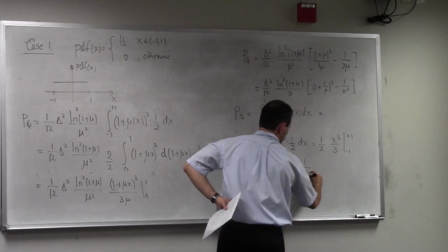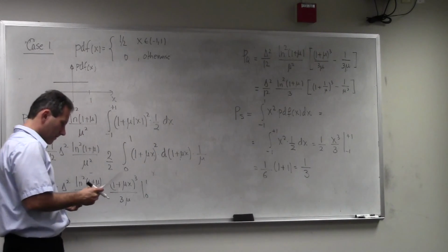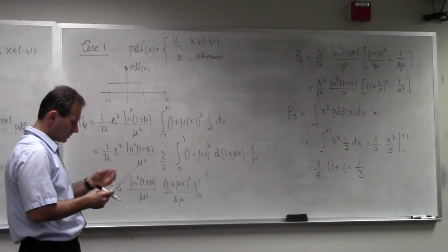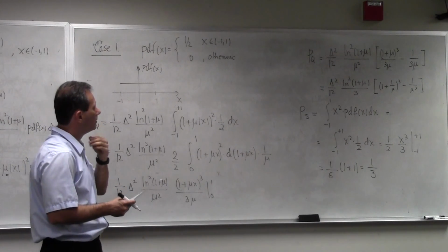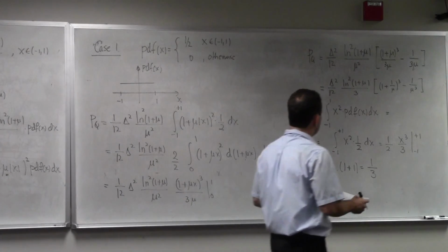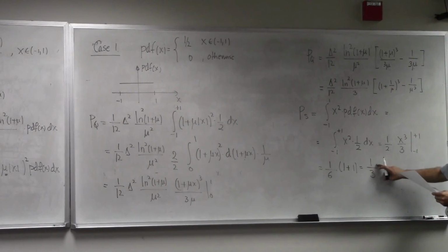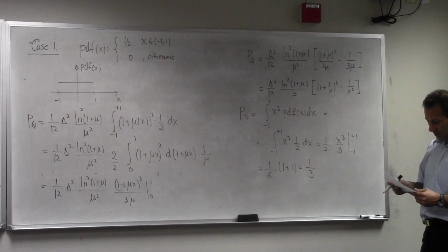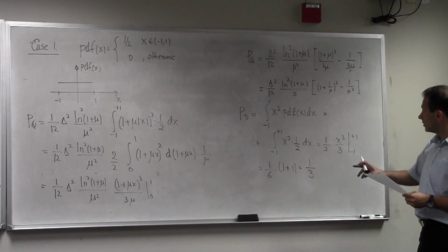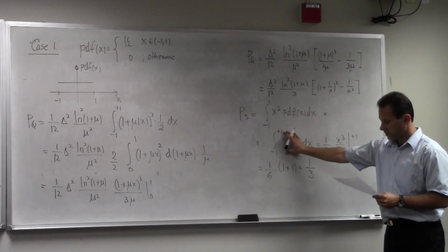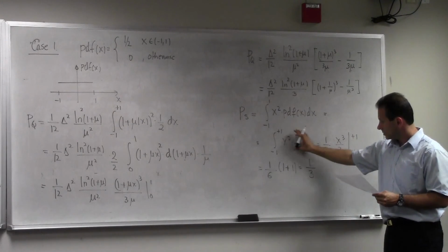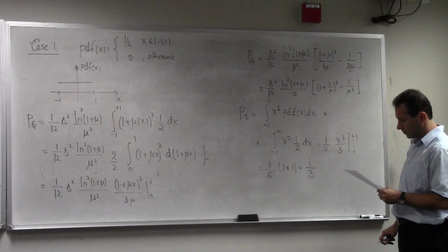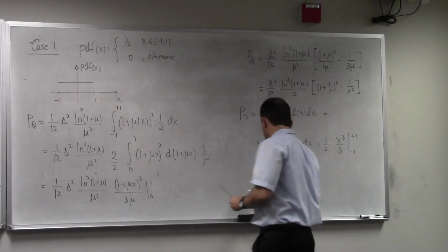So I get 1/3. So that's the power of my signal. And so that's as far as power of the signal is concerned, but I want to actually express, so this is not the best way of doing this. So let me just see what I did here. I say, well, your range here, which is 2, is equal to q times delta. So this whole 1 here is q times delta over 2 squared.